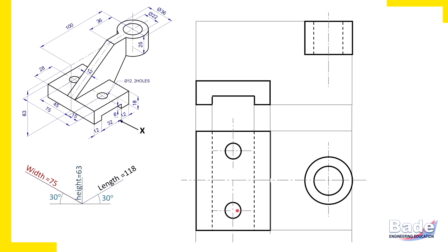Now project that hole in the front view. That is its horizontal dimension. Top view to front view, that is horizontal dimensions of particular detail you project by drawing end projectors. So this is how you draw end projectors, and this hole is in this portion of the object. So draw dotted lines. So this is how we have completed hole in the front view.